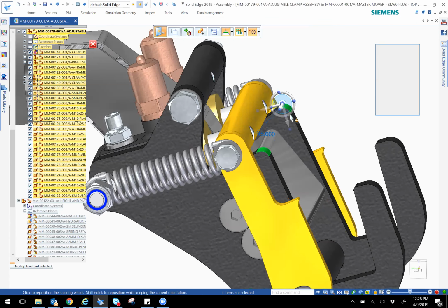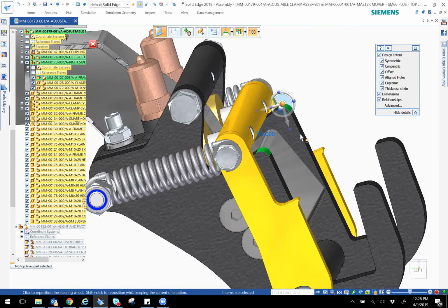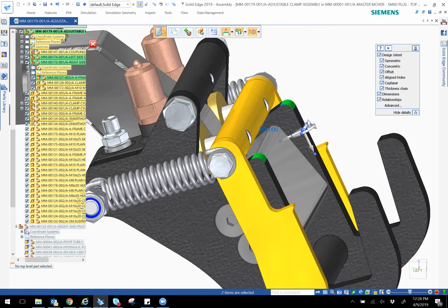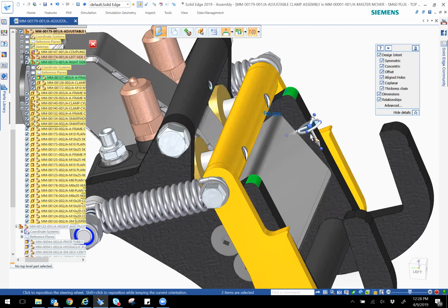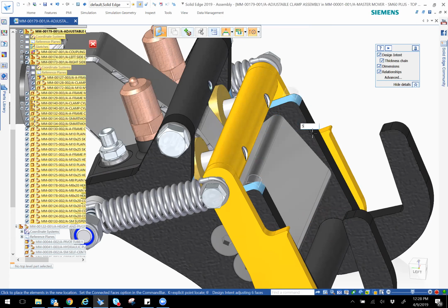And so, without even having to take this out, I can modify it. I want this to be a little bit down. So I want it to translate kind of along this axis. So just press the bottom arrow, and it should start shifting it down. And 5 millimeters should be enough.